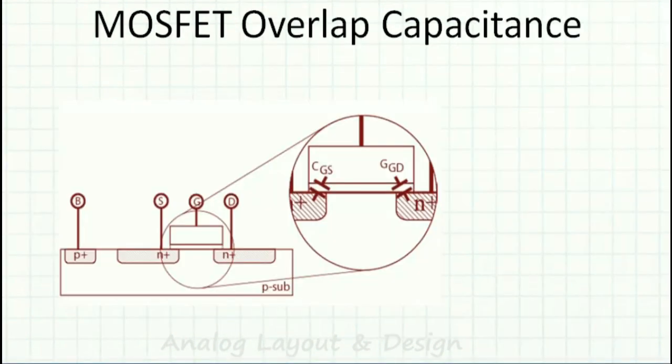Okay. Strictly speaking, I should have my capacitance like this, MOSFET like this. Okay, this is the gate. This is the drain and source. So between gate and drain, is there any overlap? There is no overlap. Gate is here, gate ends here, and source and drain happen here.